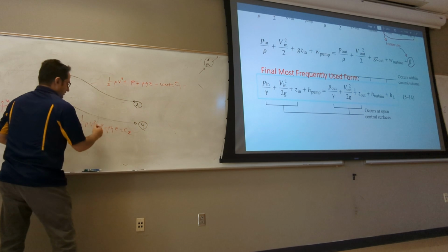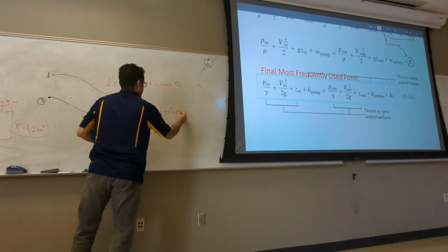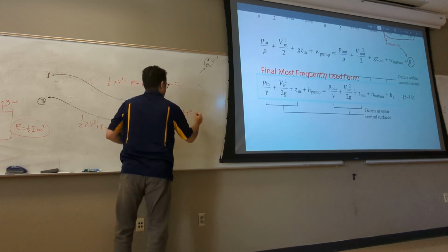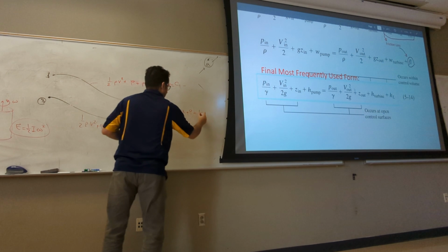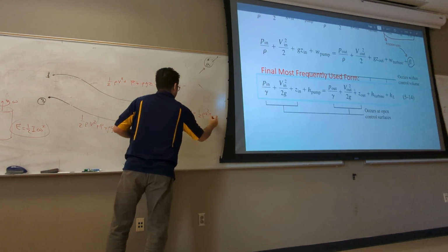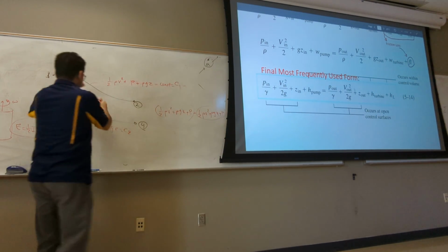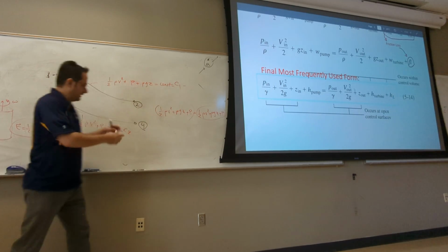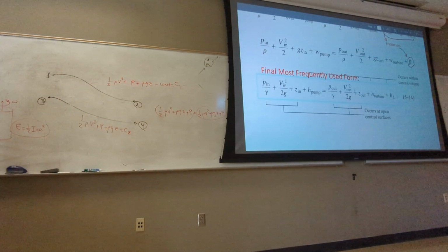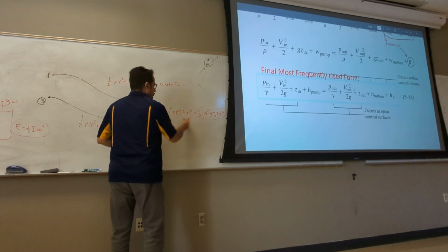That means 1/2 rho v squared plus rho gz plus P on this streamline is equal to the same sum on the other streamline. And because these are arbitrary, this sum is valid between any streamline in the flow. In other words, this sum is valid between any 2 points.